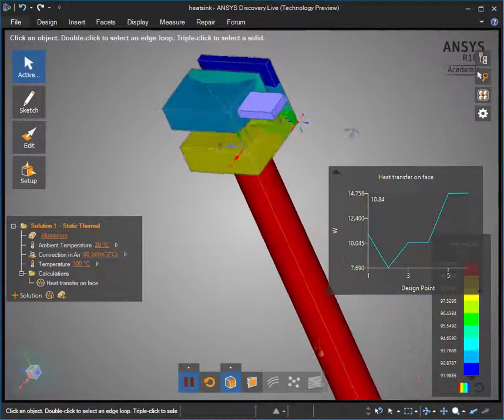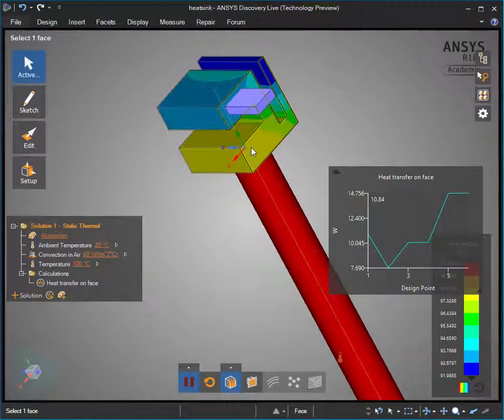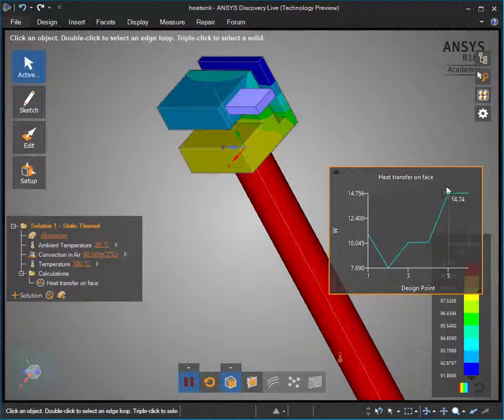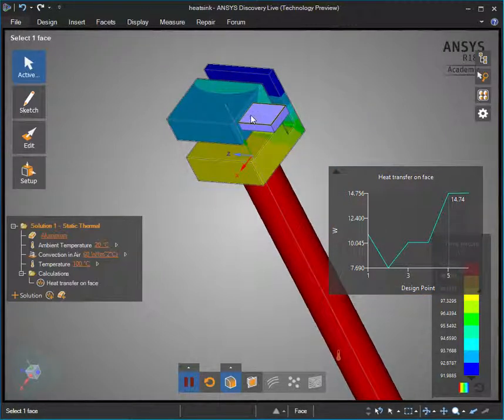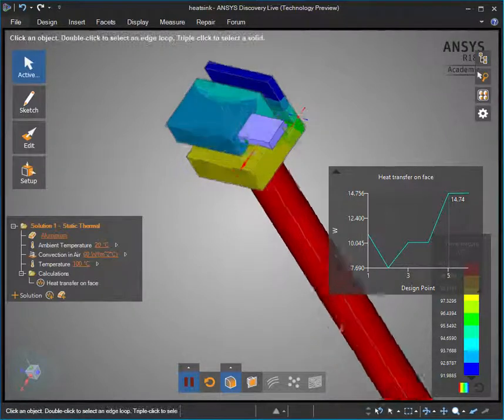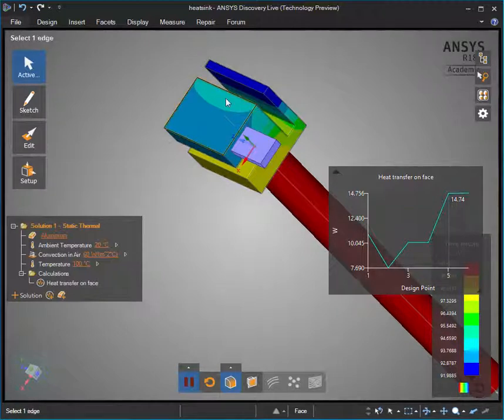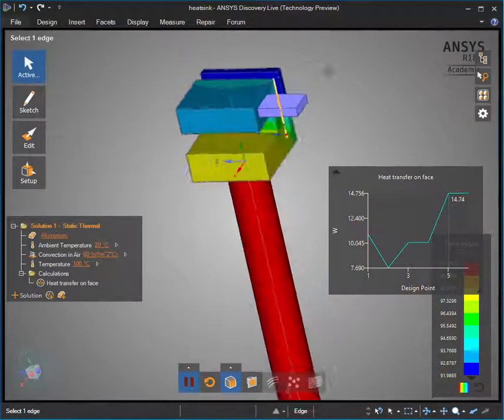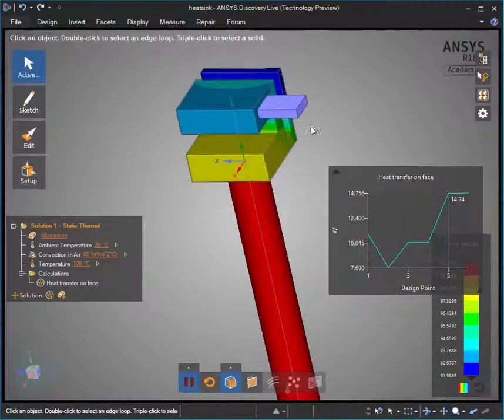So that means it isn't actually being included in our thermal solution at all. And in fact, it tracked that as a design change, but says there was no change in the heat flow. That's because it doesn't include additions outside of our original bounding box as being part of the solution. When I remove stuff from the original object, it modifies that as being like inside the bounding box, so it will be automatically included, but these extra add-ons aren't.